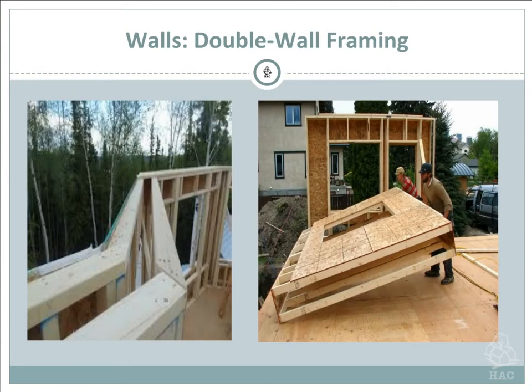This is a double wall framing. I have never seen this done anywhere, maybe up north or northeast somewhere. But again, it has its benefits and it has its downfalls. Again, you got a double wall framing, you got two walls. This inside area, like I say, is usually sprayed with cellulose. The problem with that is they usually run all their plumbing, electrical, everything inside that wall.